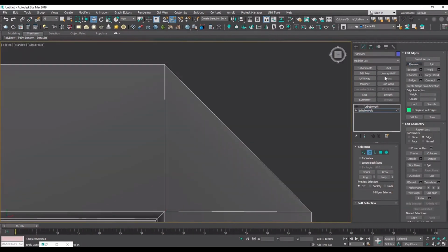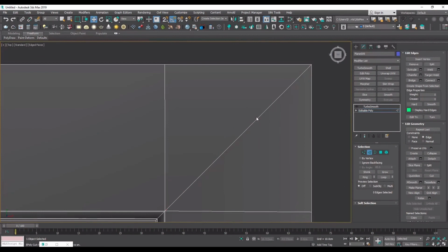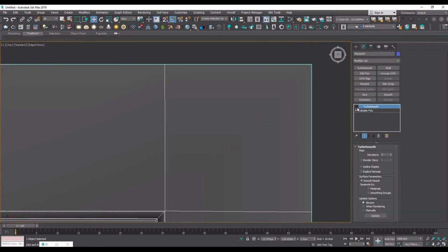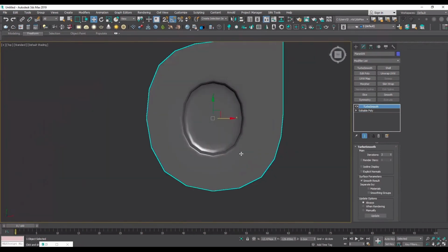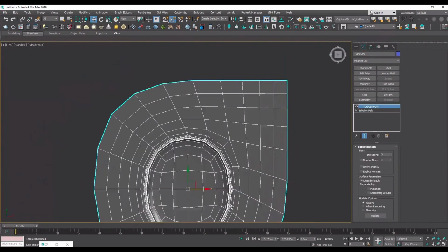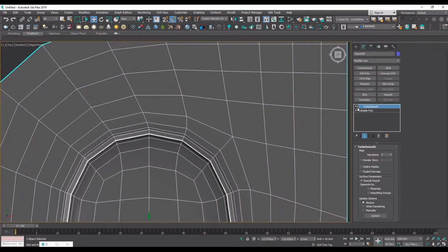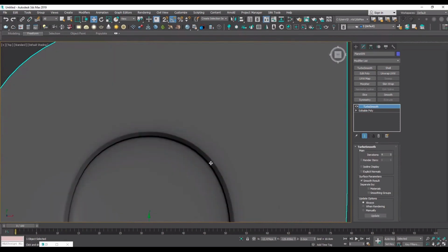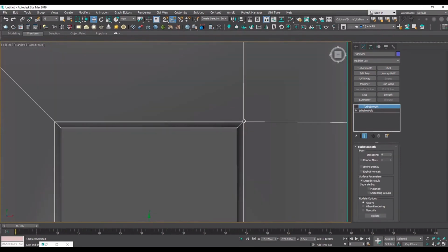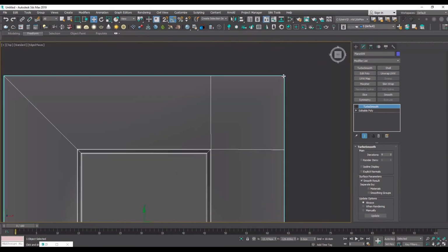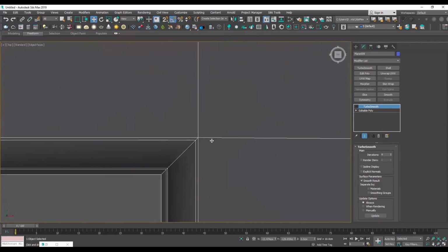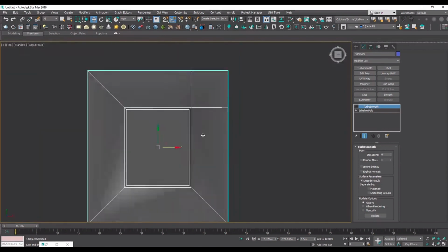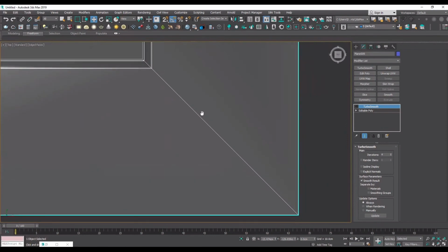To remove this extra edge only, without the vertex messing up our model like this, I should now use the remove command instead of delete. And this way, I finish fixing this part and see that there's no more circular shape on the corner that we worked on. So the key here is to maintain 90-degree perpendicular lines and also, of course, avoid the triangles.